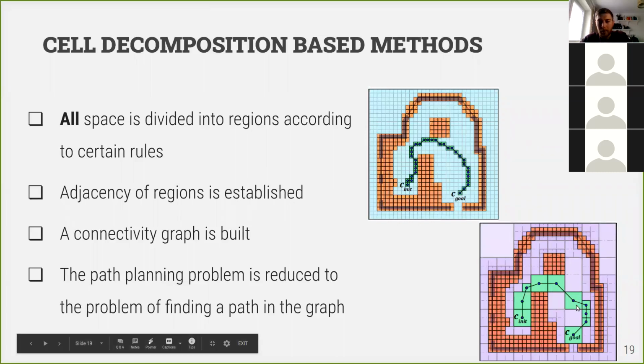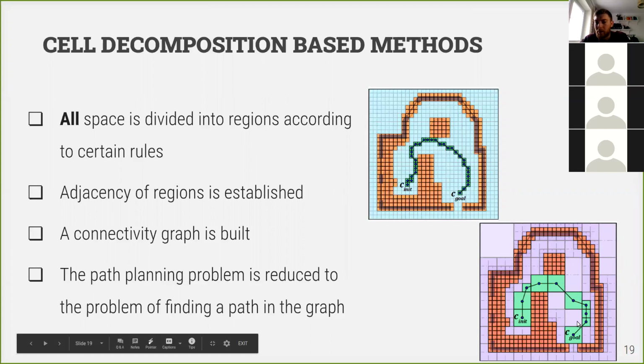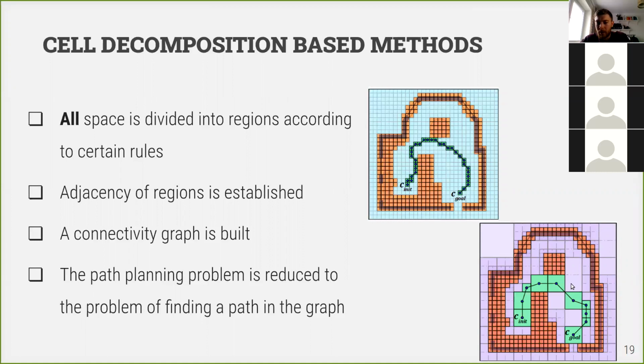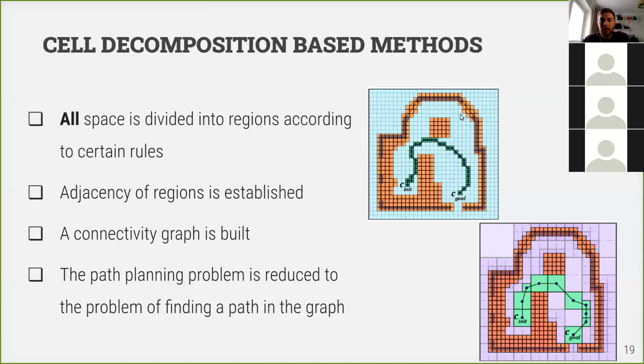This is called adaptive sampling, and what it gives us is that the computational complexity is smaller because we have to consider a smaller number of squares. So path planning algorithms will be just faster in this representation than in the uniform one, but this representation can be more complex to obtain. We usually do it in advance. If we have a map of our environment, we discretize it in advance.